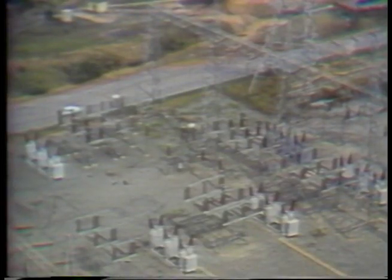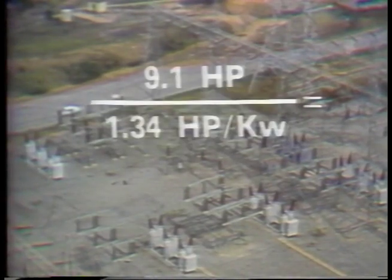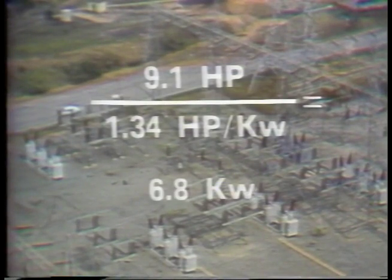Now, to determine the power used to move the load in kilowatts, we can use the conversion factor: 1 kilowatt is equal to 1.34 horsepower. Dividing the 9.1 horsepower by 1.34 horsepower per kilowatt results in 6.8 kilowatts needed to move the elevator and its load over a period of 60 seconds.